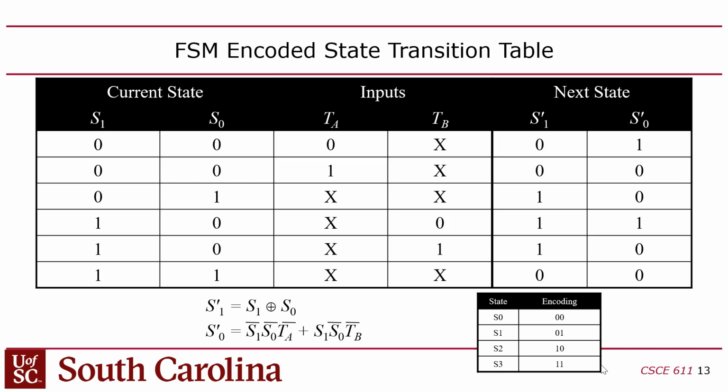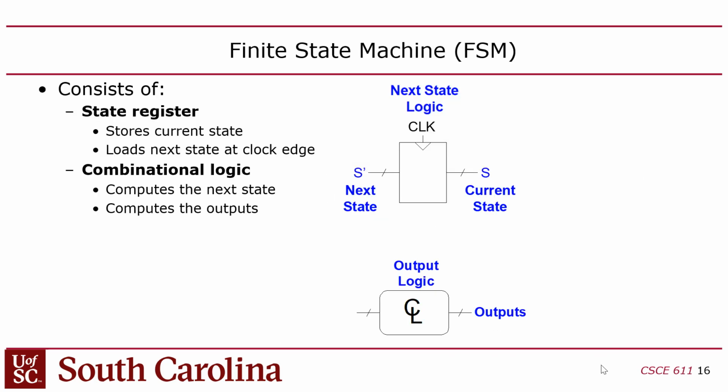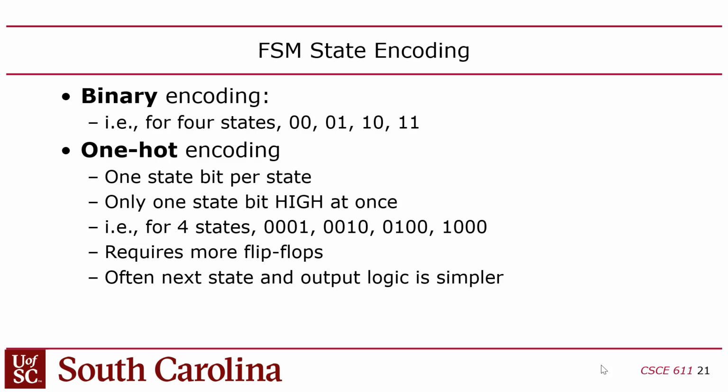Now, when I was in school, they told us that the best state encoding is actually not to use binary, but to use unary, also known as one-hot encoding, which is where if you have n states, then the state variables should have n bits, and they're all 0 except for a 1 in a specific bit position. The theory is that if you did that, you would get the minimal next state logic, right? I've never actually seen a proof of that or even seen that in action, but that's called one-hot encoding. But that was the conventional wisdom, that you should use one-hot encoding when you assign.